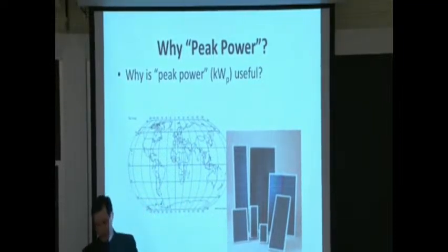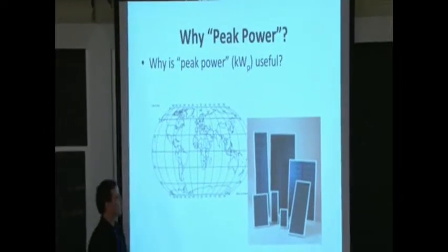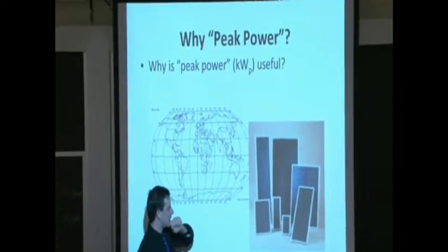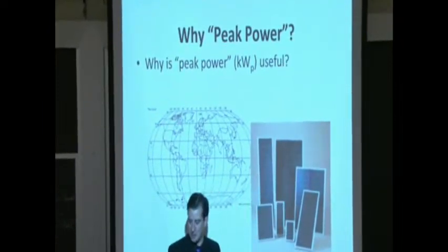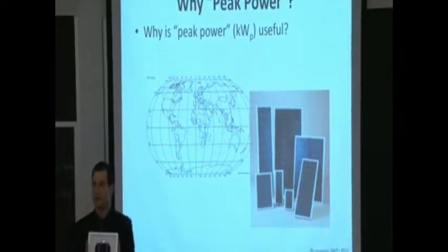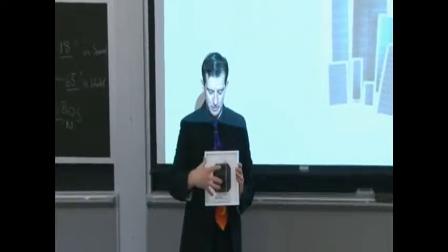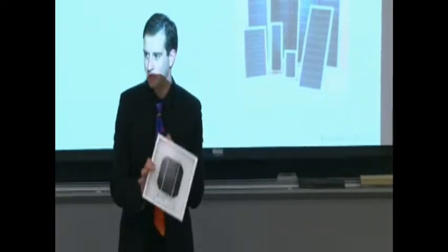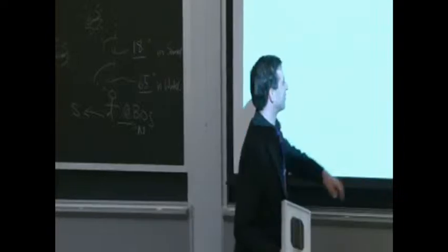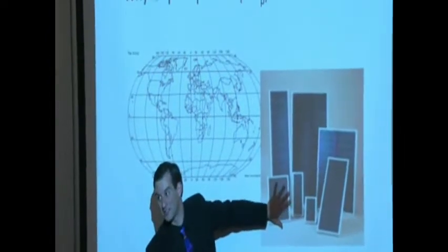And last point. In your homework assignments, you're going to be asked to size out systems, PV systems, photovoltaic systems, in different parts of the world. And the easiest way to do that is if we take a panel and we say that this panel right here is rated at a certain amount of power. So under peak illumination conditions, when the panel is facing the incident sunlight, so the cosine theta term is 1, and the incident solar resource is 1,000 watts per square meter, so around AM 1.5 conditions, this panel right here, this one's tiny, would be producing around 6 watts peak. But most of these panels over here are producing somewhere around a few hundred watts peak.